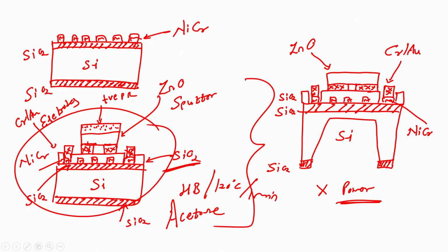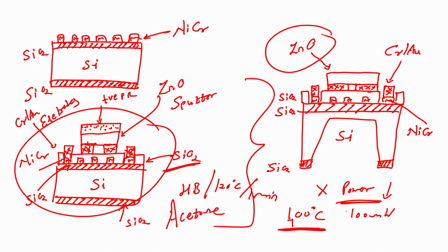Okay. Now I have to heat a thin layer of silicon, and that is why my power to heat the semiconducting oxide will reduce. So, to obtain let us say 400 degree centigrade, earlier we required let us say 100 milliwatt of power. Now, for the same temperature, if you want to reach 400 degree centigrade, I will require less power because of my micromachining.